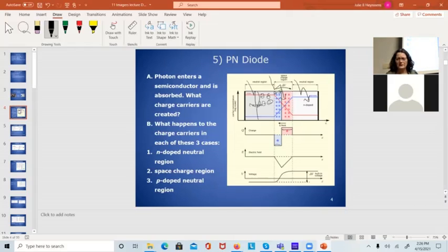So we're going to slowly discharge the depletion region. The voltage across the depletion region will go down as the amount of charge in there goes down. And when we read it at a later time, we let the light come in for a little while, a few seconds, a few hours, a few milliseconds, depending upon how fast you want to do it. And we read the voltage level a little bit later in time, and we compare the initial voltage to the final voltage, and that's the amount of signal we have.